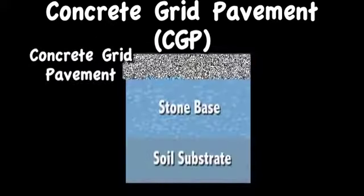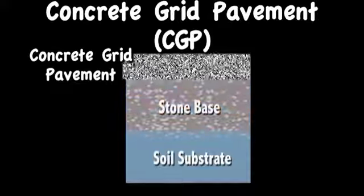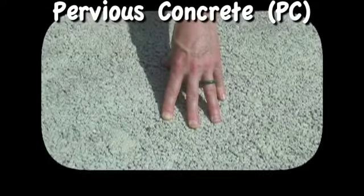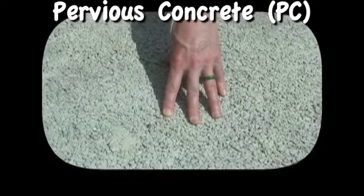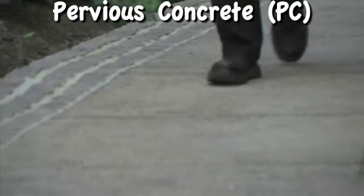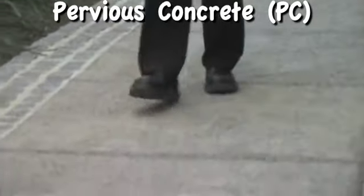While the installation techniques are similar for base and bedding layers, an experienced contractor is generally required to manage the grid layer. The fourth type of permeable paver is pervious concrete, or PC. When installed, pervious concrete looks like conventional concrete. However, it allows rainwater to flow through it into the bedding and base layers for infiltration into the ground.